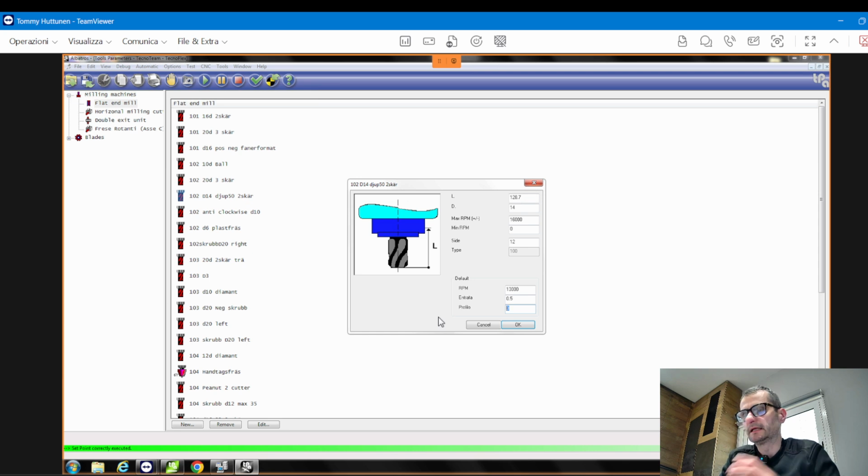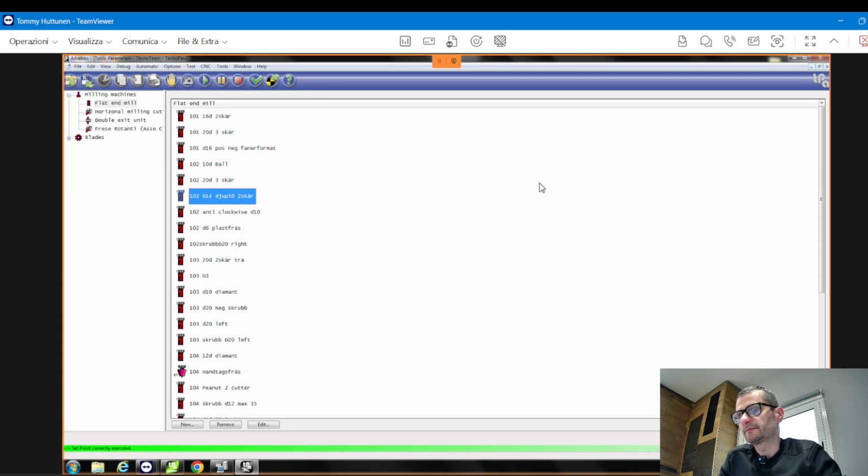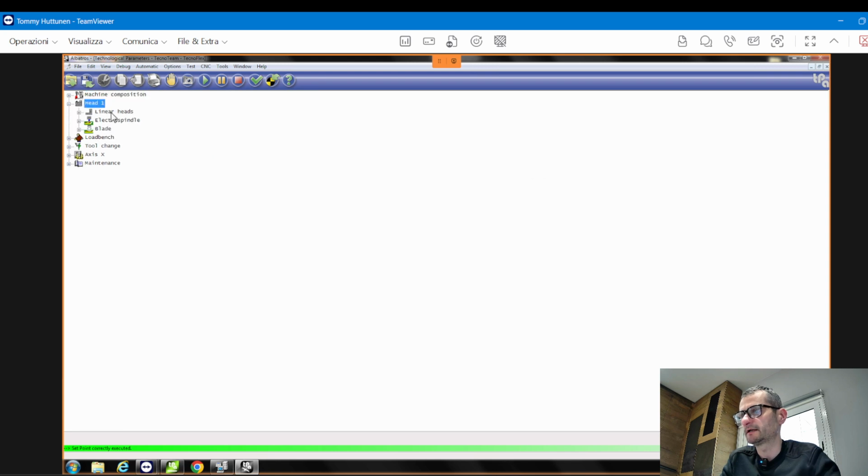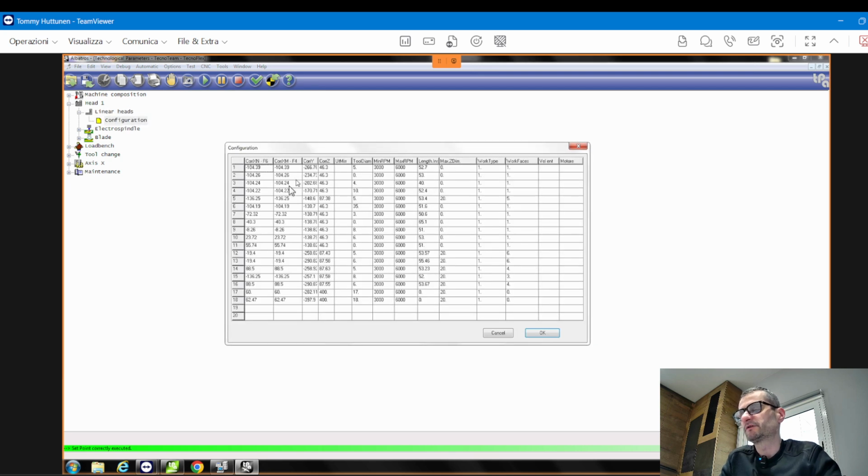Okay. How to create in AlphaCam your tool for bore? As I told you before, you come back here to the technological parameters, 8.1, linear adds and configuration. In configuration, you can say, for example, the spindle number doesn't matter for us. You can put the spindle number as you want in AlphaCam configuration.